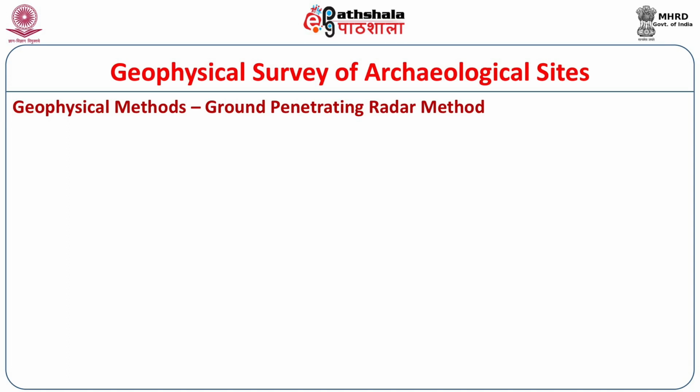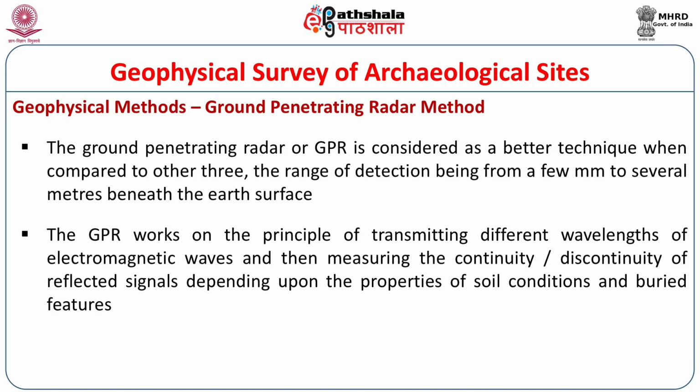Next comes the ground penetrating radar. This is one of the most suitable techniques used by many archaeologists and even by geologists. They use it for detecting subsurface features. Even geological deposits can be measured here. It is a tool with detection ranging from a few to several meters beneath the surface. Depending upon the antenna we are using, buried features ranging from a few meters from the surface to several meters can be detected using this principle.